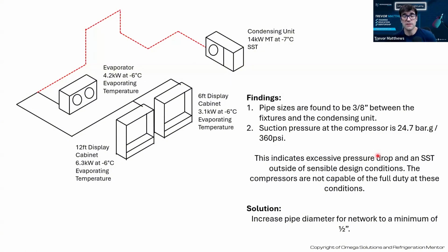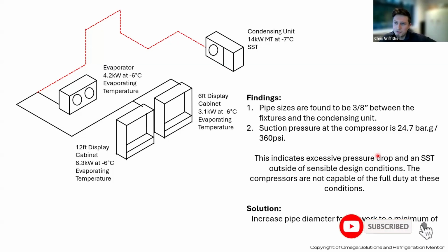Like, you can go in, and today with CO2 systems, we've got pressure transducers on almost all the evaporators. Well, we do have them on all of the evaporators, so you can compare that to your suction header pressure. Yeah, it can be quite drastic. When you say 1 bar, 15 psi pressure drop, if that was on an HFC system, well, you haven't got any chance of your compressor running accordingly there. If you're on a low temp 404A system, you'd be running nearly in a vacuum at that point.